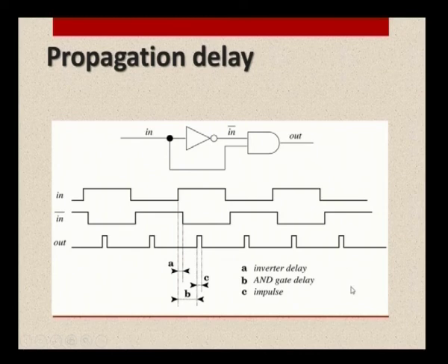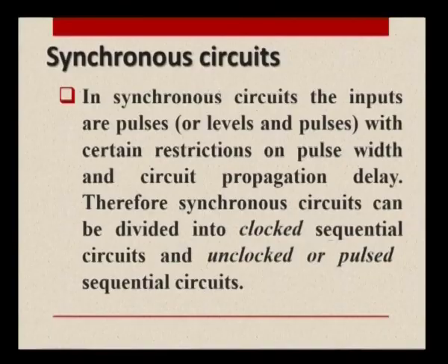So, this diagram is also a self explanatory diagram which tells us the output of the circuits would also have a delay. So, instantaneous output we may not be able to expect in some of the circuits. When the circuit is very big and complicated, the propagation delay naturally happens. So, this will also alter the duty cycle. So, accordingly we should design the circuits. Now, let us try to define what is a pulse.